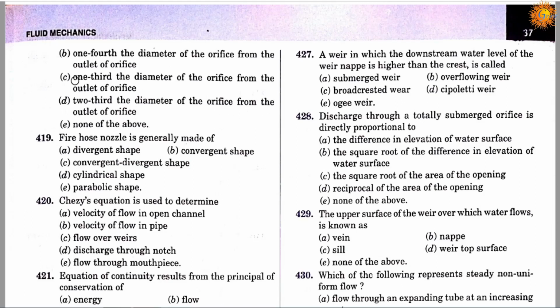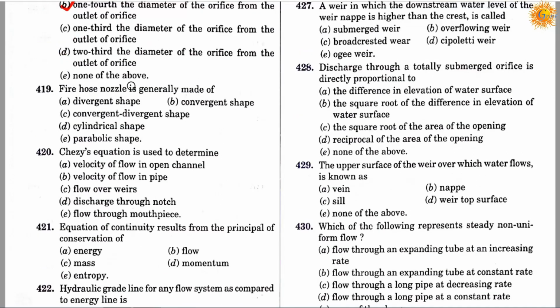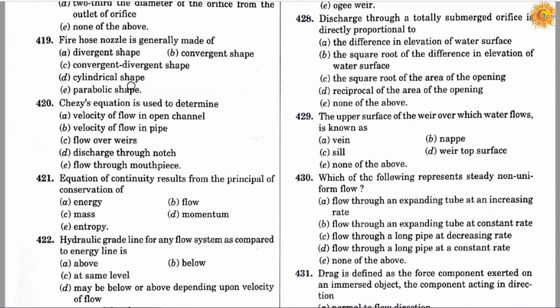Correct answer is B, it will be 1/4 the diameter of the orifice from the outlet of orifice.